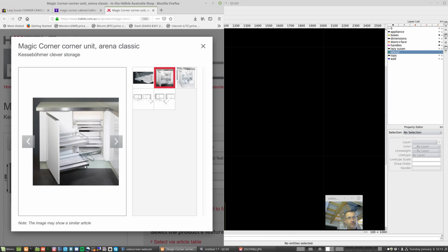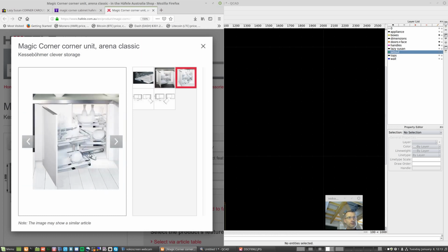But in both cases, there's a limit. If you look at between that shelf and that rail, that's reduced our height. There's also the clearance underneath that is lost, which doesn't show well in this photo. You've got the thickness of the rail and a bit of a mechanism there. Maybe that one shows it better. You can see there's a bit of mechanism space here, which it needs, operating clearance. So you lose height, and you lose height again, and you lose height again with the objects. So at the end of the day, you may only get the same volume, just do your sums, it doesn't take long to work it out. We're losing about 80mm here and about 60mm there.